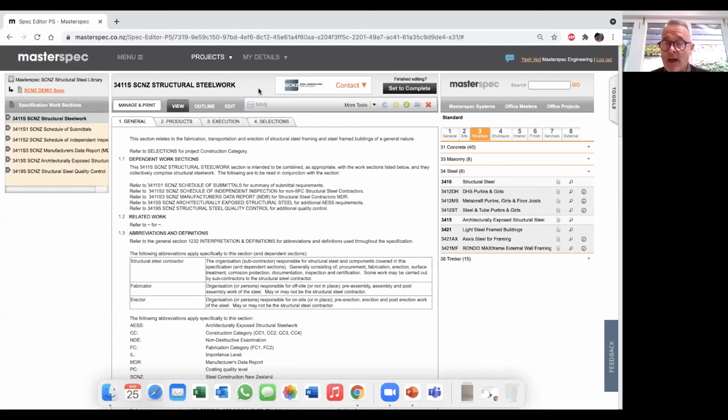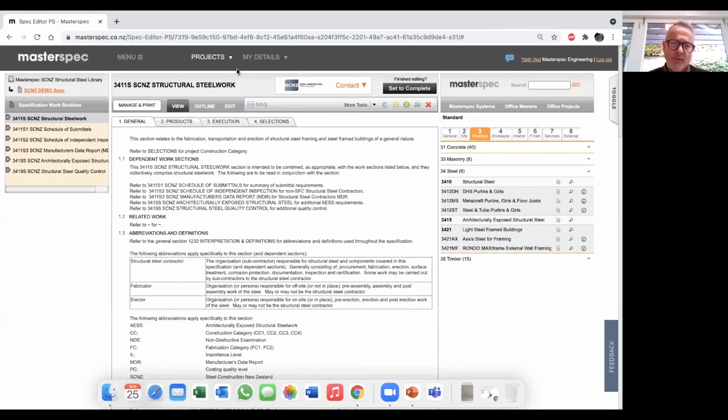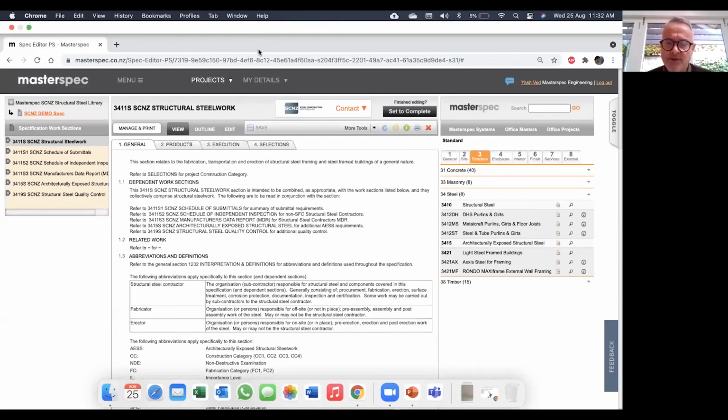Pass. I mean, this would cover the steelwork up to that point where they are connected, and presumably, there's a number of connections for insulated panels, from nylon bolts to various other mechanisms. So it would depend on the systems used. If it's nylon bolts, then presumably they would connect to an angle of some sort and be bolted through. So the structural steel would cover up to that point of inserting a bolt of some other material, probably. Because I think the other thing to consider is the scope of the standard as well, as to how far does it go in covering the enclosure or the building.